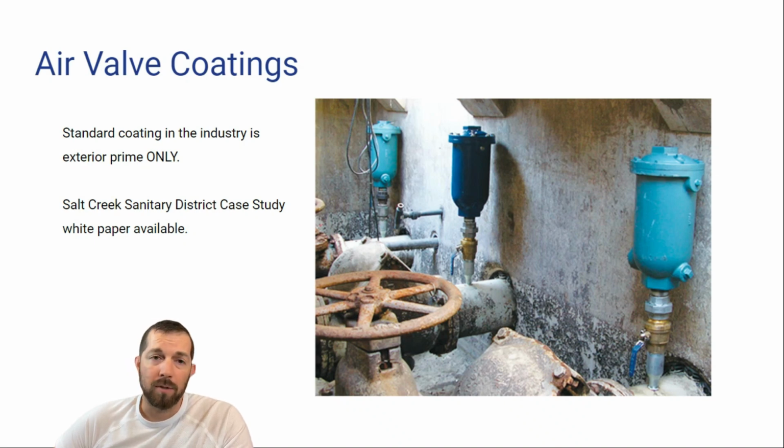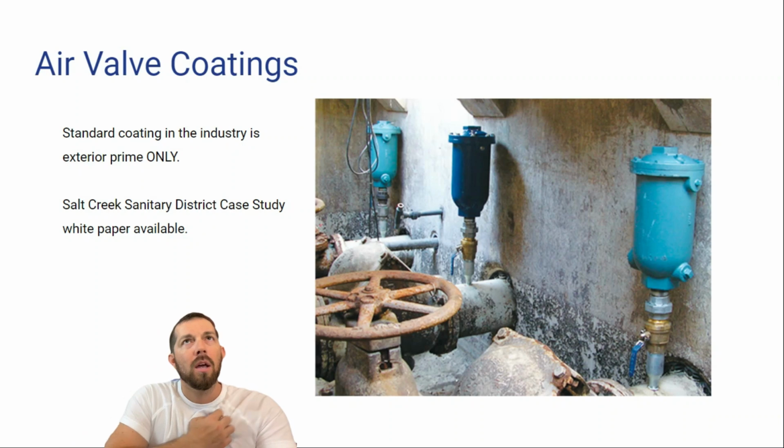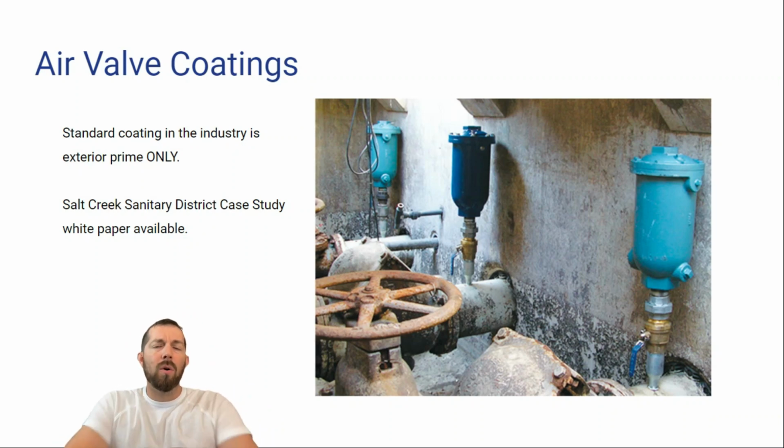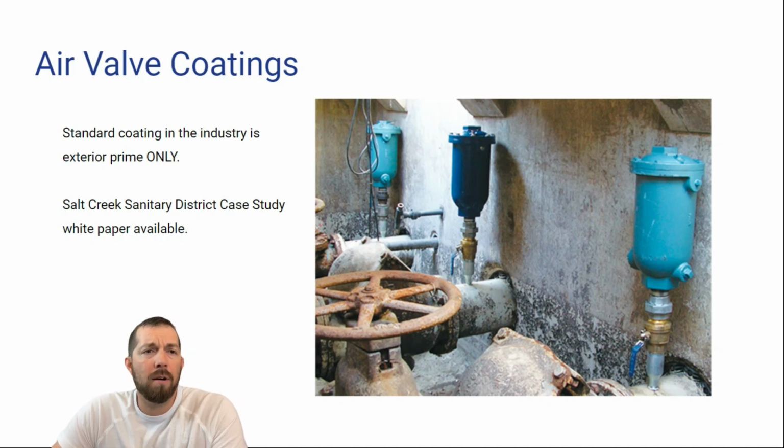When you're talking about specifications, standards, these are things to consider. I mentioned hardware as well. So hardware, these air valves, they go into vaults. They're out in the open. Maybe they're exposed to the elements. It's not a lot of extra funds to standardize on stainless steel hardware for these air valves as well.